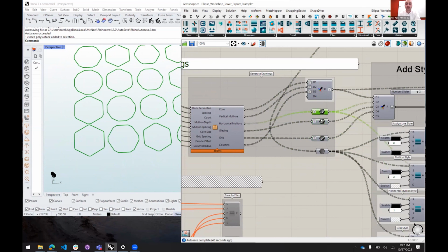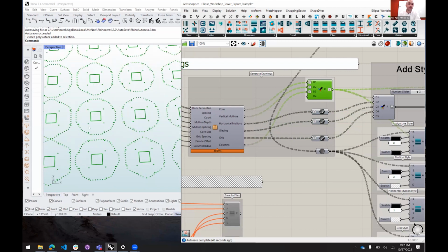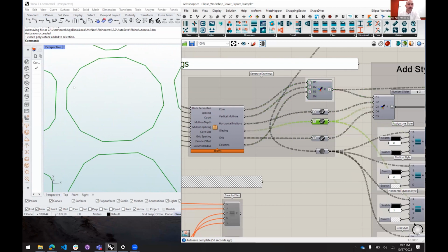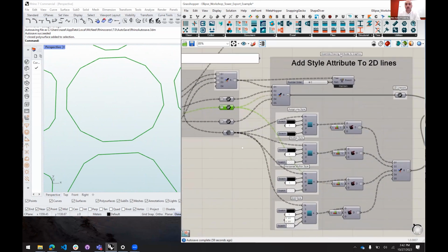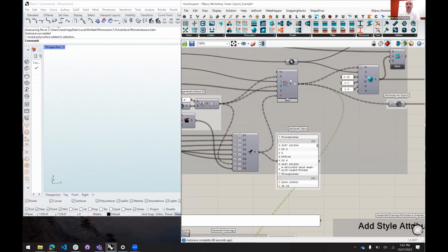So we have all these different line layers, and we want each of these to be displayed a little bit differently. Like we want a really nice fine line weight for some of our small geometry, but say the outer perimeter of our floor plate wants a thicker line weight. What we do is we take our attributes from above. We created all these attributes.